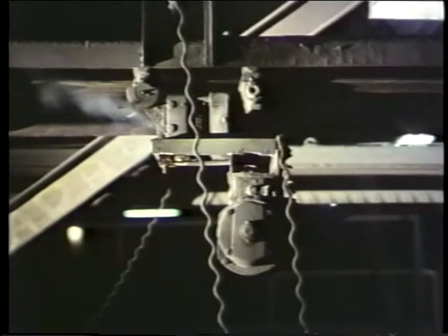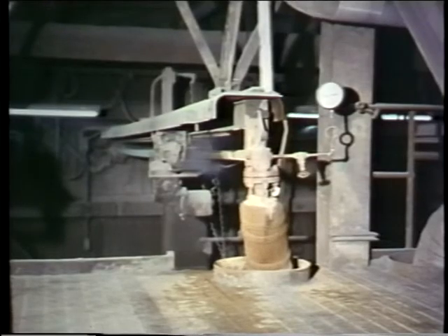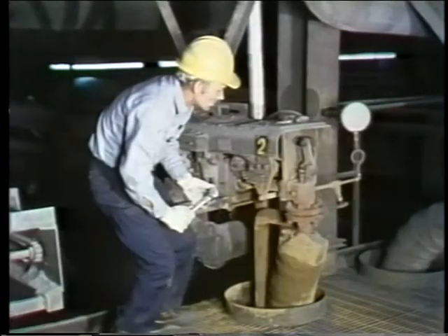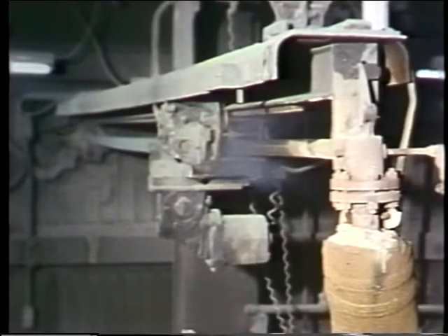But what happens if a soot blower is bound up tight and won't move? It could be packing that's too tight, or it could be warping of the element or feed tube on a long retractable like this one. Whatever the cause, the thing you're most likely to have to do is drive the thing home manually. Some provision is made on most soot blowers to do this. It may have a drive shaft that runs the length of the support channel, so a wrench can be used to turn the drive, or some soot blowers have a hand wheel and chain to drive a soot blower that's binding. The important thing is not to shut off the blowing medium.